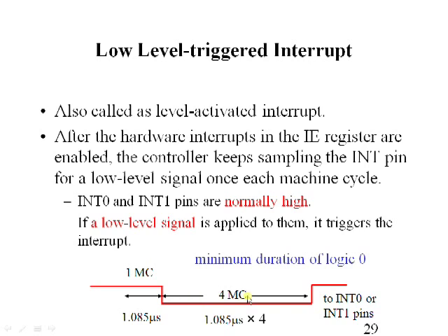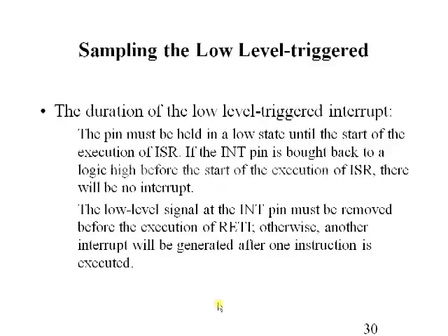Okay, and this logic low level should be maintained for 4 machine cycles so that the processor can recognize that particular interrupt. For the duration of the low level triggered interrupt, the pin must be held in a low state until the start of execution of ISR.